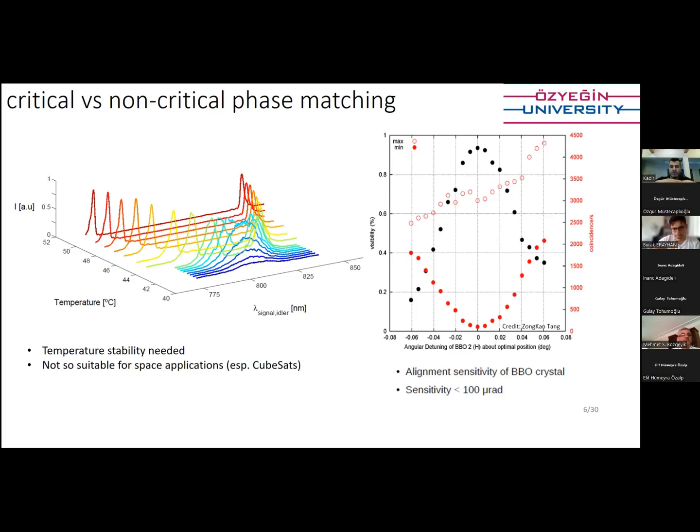If you want to cool down, you need to dissipate the energy of the other side so that effectively you cool down the system. And to dissipate the energy on the hot side, you put a heat sink, which means a large surface area metal, usually aluminum or copper, so that the atmospheric gas molecules keep hitting it and taking the energy out of this metal. That's why you want to increase the surface area of the metal. And you can do this because there is atmospheric pressure, right?